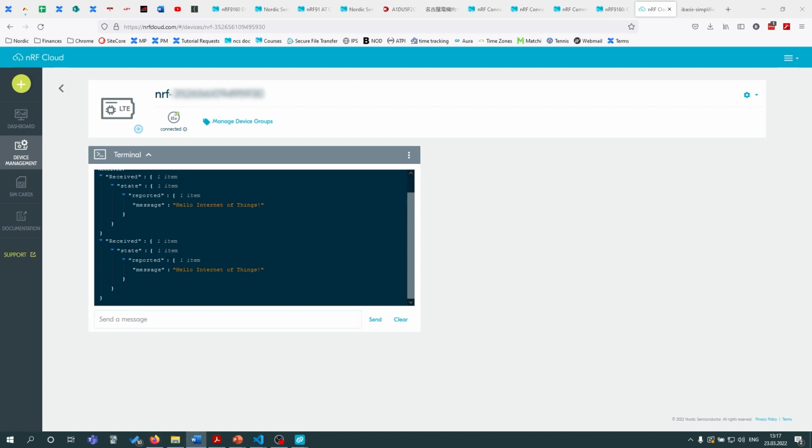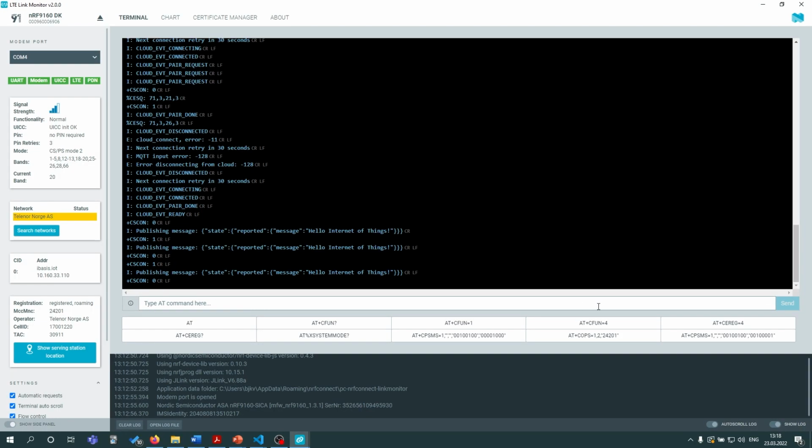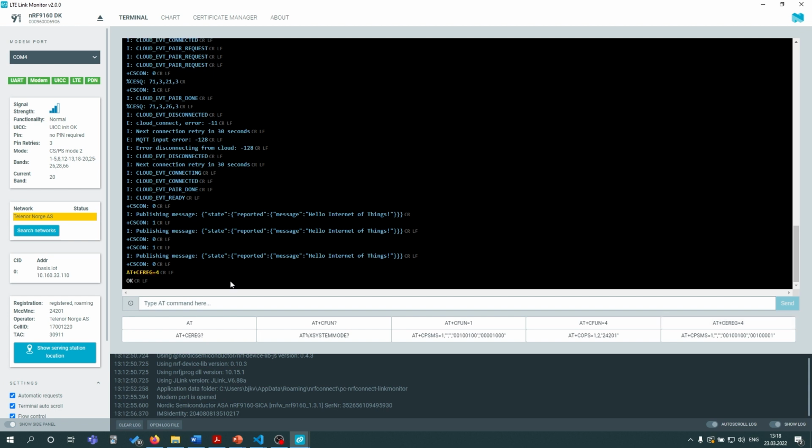Now what we'll actually do is we will turn off. It's always a good idea when you're doing this, if you want to make changes, if you want to reconnect, or I guess reattach to the base station, always turn the modem off, because otherwise, worst case, the base station might actually throw your device off the network if it's trying to attach too many times in a short period, and then you'll have to wait, I think it was like 15 or 30 minutes before trying again.